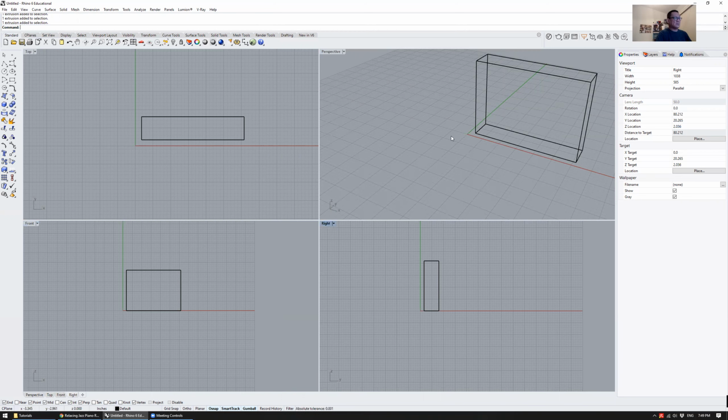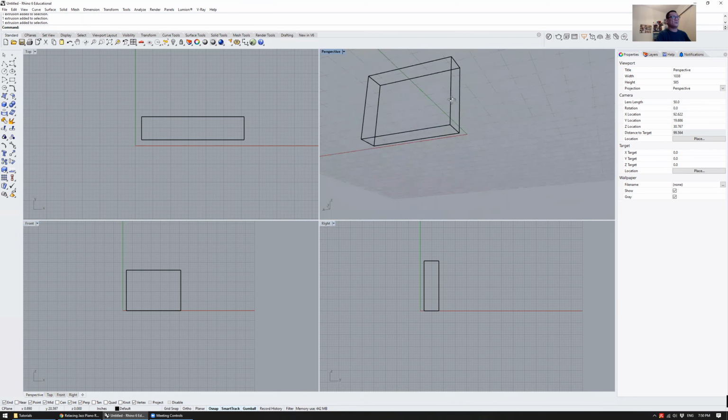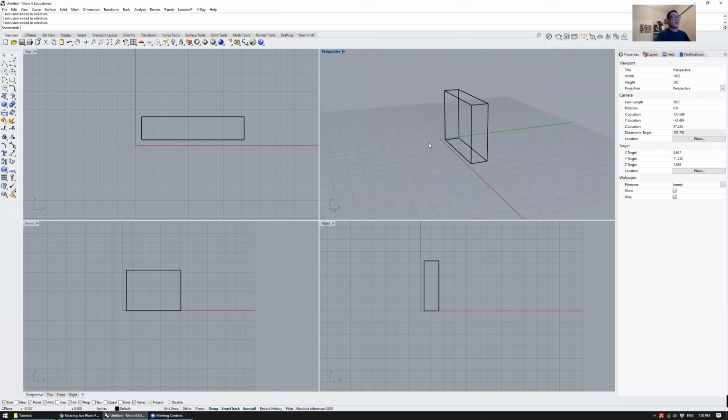Now, this behaves a little bit differently in one of these 3D views. The right click button actually rotates you around a certain rotation point or axis that you can set eventually. The zoom button still works the same way. To pan, you will have to hold down the shift key while you hold down the right mouse button simultaneously. So you're able to pan in the 3D view. Otherwise, it will only do rotation. So you add the shift key to pan. Okay, so that's really basic navigation.